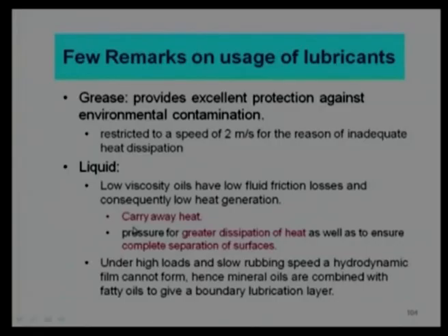Now, these low viscosity oils are also preferred from the cooling point of view. That is why I say they can carry the heat. In addition, they are preferred from the feed pressure point of view. If we are trying to levitate one surface over another surface, or keeping a separation between the surfaces, sometimes we force feed the lubricant and pressurize the lubricant between the two surfaces.